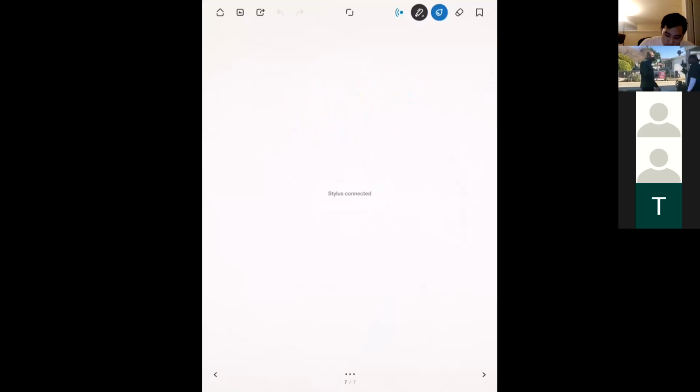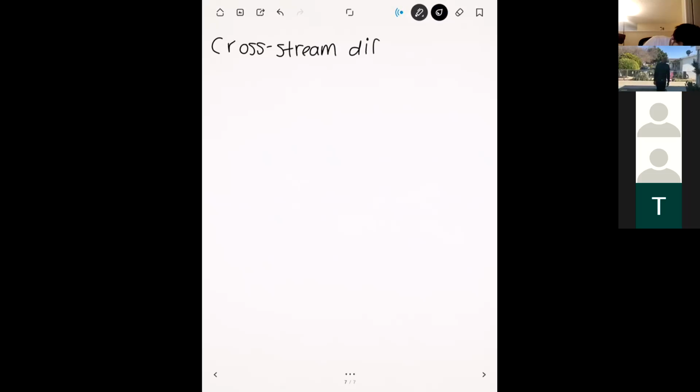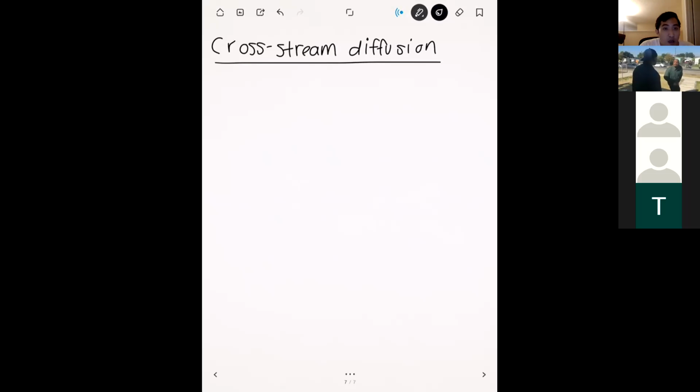What can happen sometimes, which is mostly a bad thing but also unintentionally a good thing sometimes, is that you have some additional diffusion in 2D. In 2D situations with both basic convection and diffusion, depending on the direction of the velocity field, you can have some additional artificial diffusion.